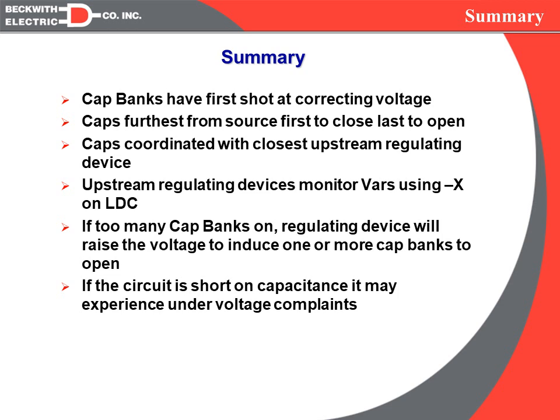We want the cap banks, though, when they do correct the voltage, to be coordinated in such a way that the cap bank closest is the last one to close and the first one to open, because it has the least impact on the voltage. We want to keep that end of line voltage up so we can flatten the profile out. So we want to start by getting the voltage up at the end of the line and raising it towards the front end of the circuit.